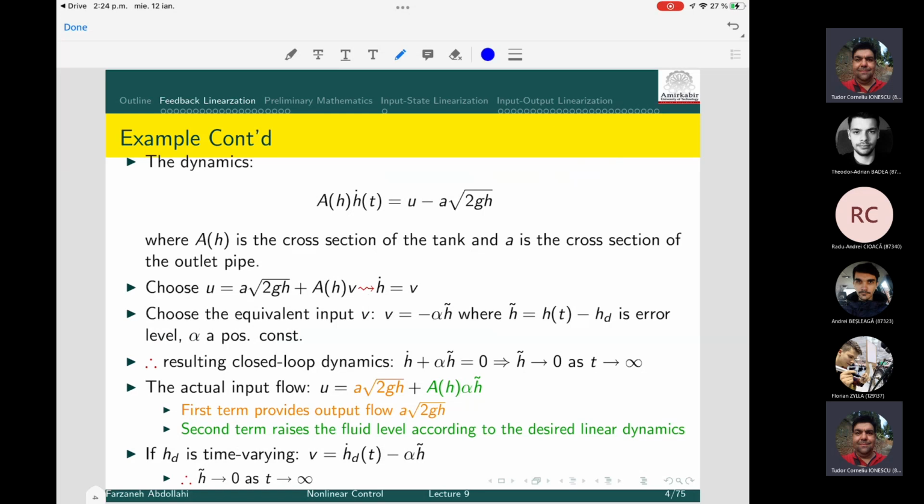You know, a more complicated tank, so more design. A different kind of model, essentially the fluid level you have in the toilet. If you want to do a simple control, you linearize it in open loop, just like we learned. You do a simple linearization around some equilibrium point, and then you do a linear controller based on that. And you see it's working. Your toilets do not spill over.